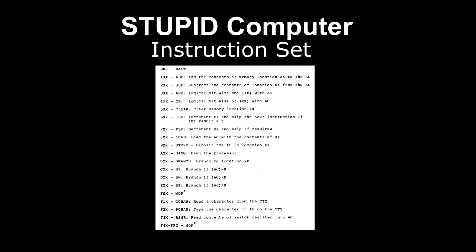There's a branch, or a go-to, or a jump, whatever you want to call it. I called it branch because it's opcode B, and then it's branch if 0, branch if negative, branch if positive. Okay, then a whole bunch of no-op instructions, only one of which I would actually keep if I expanded the instruction set. I defined a get-char operation, but because of the limitation of just the 2 inputs on the B bus, that didn't get implemented.